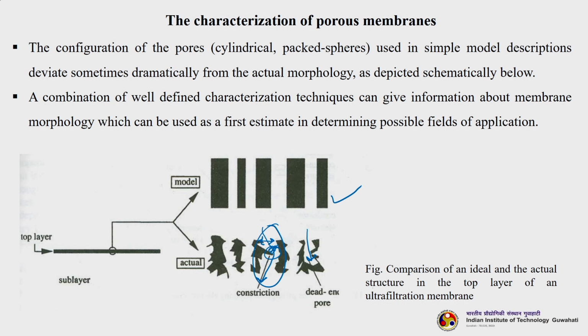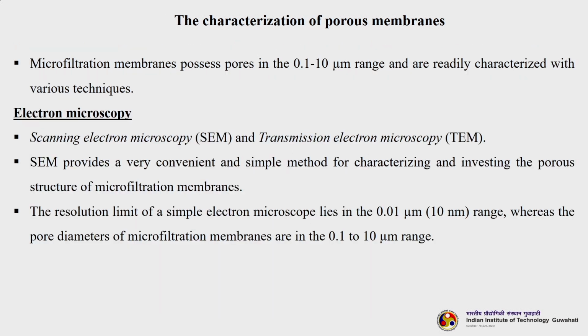And this is not contributing to your separation. Microfiltration membranes possess pores in the 0.1 to 10 micron range and are readily characterized with various techniques. So, let us start discussing techniques. Today we will discuss three: SEM, TEM and AFM.